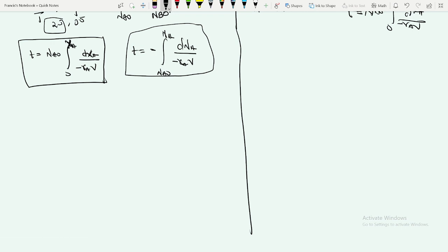And to do that, you are going to use this equation because this has conversion in it, right? And sometimes you might be asked to find the moles you made after a certain time in the batch reactor, and then you can use this. However, you can still use this, but then after this you have to solve further before you can get what you want. But when you use the specific equation, you just get your answer straight away. We'll see more questions on that.